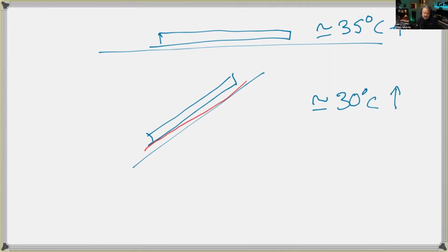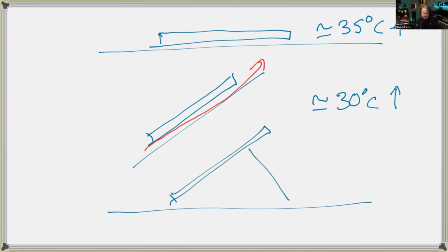So heat will start to go up the back and cause a small amount of convection, which gives you a 5 degrees drop in temperature, which actually will give you about 1.5% more power. So actually it's probably more significant than the color of your panel, the way you mount it. Horizontal, worse; inclined, better; and best is, here's our flat roof, putting the panels on tilts.